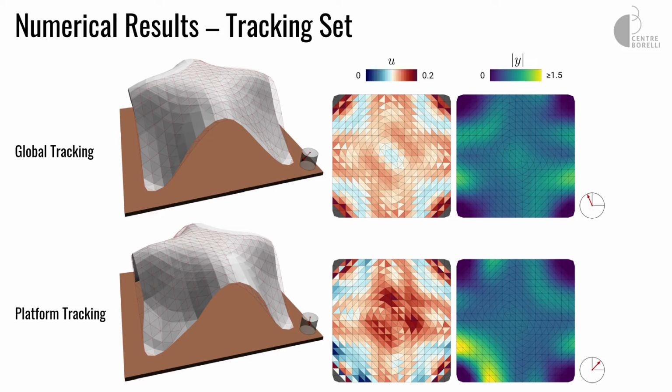And then we see that what happens is it builds some reinforcing structures. You can see some bars that reinforce the top from the side elements, and also reinforce these corners. You can maybe note that the small triangles in the corner are fixed, like boundary conditions, they're just clamped. Then extra material also reinforces it to make it more stiff. And you can see you have some displacements. This is always the used material. This is the norm of the displacement, and you can see you have some displacement area on the top, for instance. It already gives some nice reinforcing structures, but this is not really the effect.